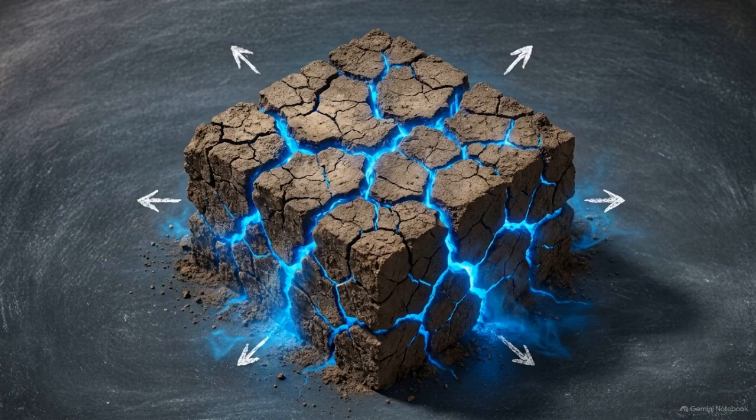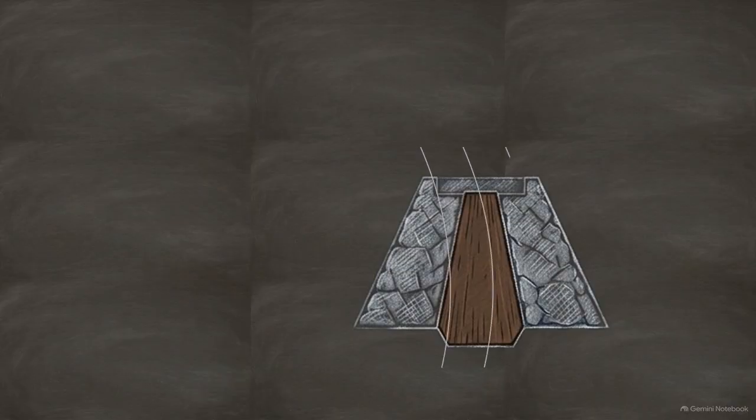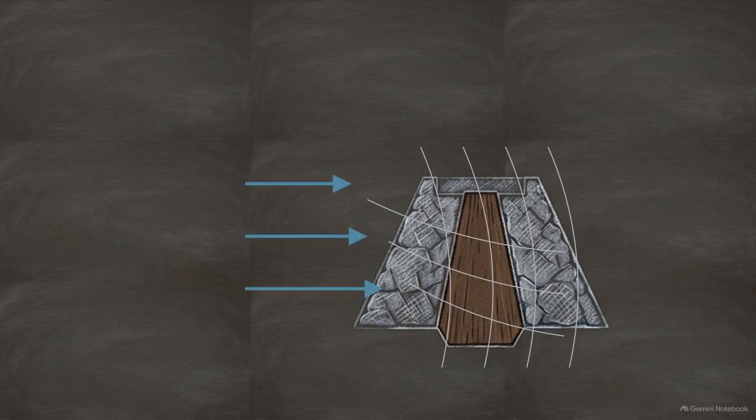Yet even the most accurate geometry calculations can be rendered useless by the most volatile variable in geotechnical engineering, internal pore water pressure. This diagram shows a steady-state earth dam holding back a high reservoir of water. The flow net inside the cross-section represents the gradient of internal pore water pressure. Under these conditions, external water actually provides stabilizing hydrostatic pressure against the dam's face.